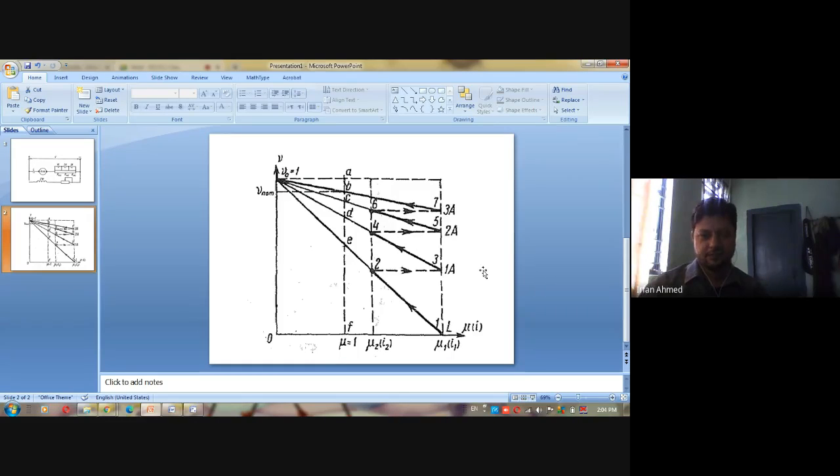If you allow 5 to 6 times the rated current to flow through the motor, your motor armature circuit might get damaged. So you cannot allow it even at the time of starting, even for a very small duration. So you have to limit the current. To what value has it to be limited? That is decided normally by the armature conductor's current carrying capacity.